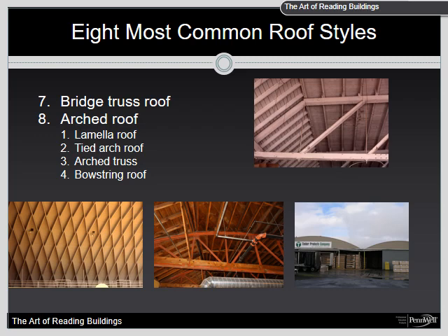Hazards. Although most heavy wood roofs of this type can be substantial, the age and size of the lumber and the span of the arches determine the hazards. Some bowstring arches are comprised of iron, steel, or a combination. These roofs are often found on commercial warehouse type structures, the content of which may increase the risk of rapid exposure of fire to the underside of the roof structural members.